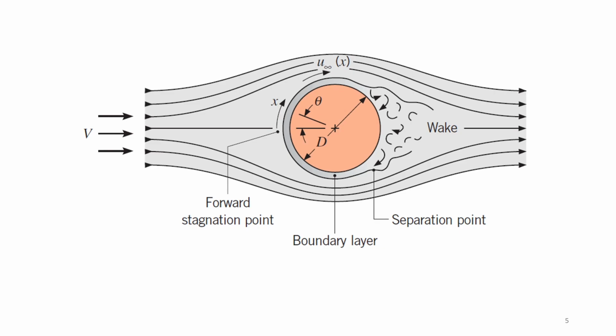Before we go into the actual convective heat transfer coefficient, let's summarize some of the observations from the videos. One observation is that there is a stagnation point at the front. When the fluid comes directly towards the tip of the cylinder, it is going to stop because it is like a barrier. Then you will have a laminar flow forming around the cylinder, and eventually this laminar flow is going to separate. After the separation, you will have a turbulent region. We call this region the wake.